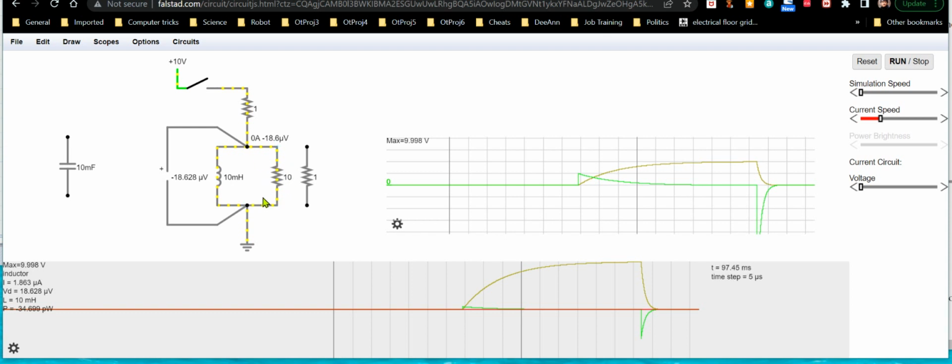So if I put a 100 ohm resistor here, for example, it would generate a 1,000 volt spike instead of a 100 volt spike. And if I were to put a 1K resistor here, that's 1,000 times that. So it would generate 10,000 volts across it. The problem is a real resistor may not be able to handle 10,000 volts. Believe it or not, resistors have voltage ratings on them, and typically they're only 200-300 volts if you're lucky.